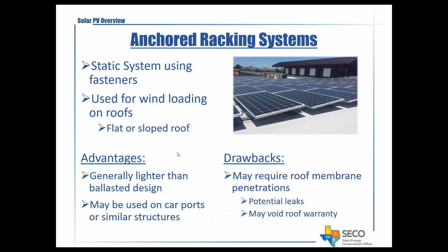Some of the advantages are they're generally lighter than the ballasted design, and they could also even be used on other applications such as carports or similar structures. So if you have some covered parking on your properties, then these could potentially be an option there as well. Some of the drawbacks include that they may require roof membrane penetrations, and this could potentially lead to leaks down the line. Usually when the contractors install it, there are procedures to avoid leaky penetrations, but over time, some of those seals may fail.